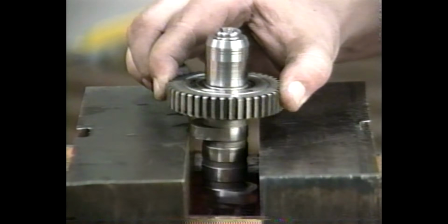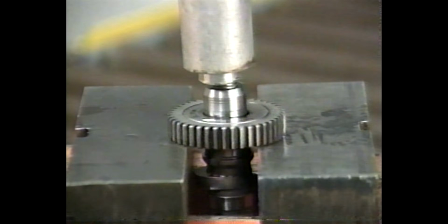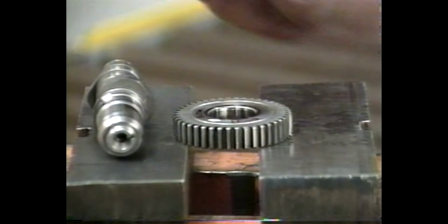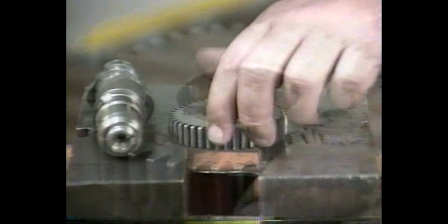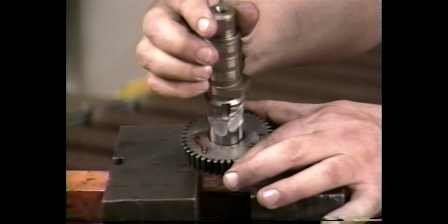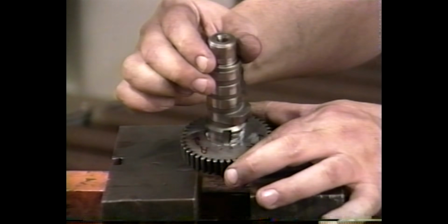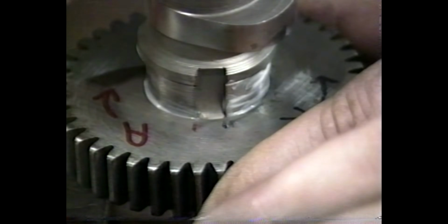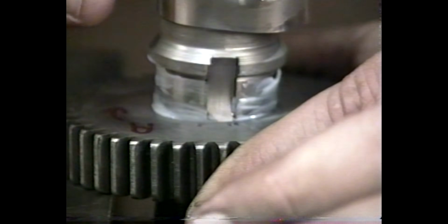Going to our press, we rest the drive gear securely on a set of parallels and gently press the camshaft out of the drive gear. Next, we flip the drive gear over on the parallels so that the factory timing marks are facing downward and we can plainly see our marks. We lightly grease the camshaft to make reassembling easier. Then, using the black mark and the penciled line on the drive gear as our guides, we carefully insert and rotate the camshaft until the black side of the locating keyway lines up with the inside edge of our penciled line on the drive gear.